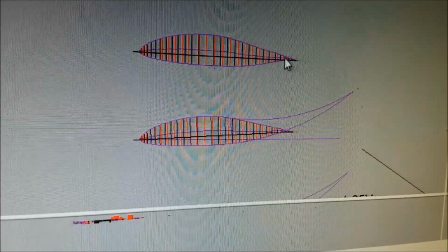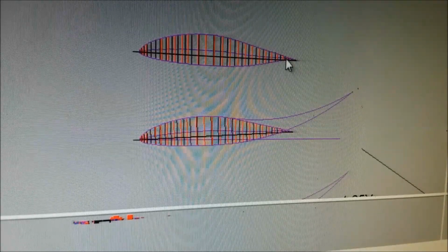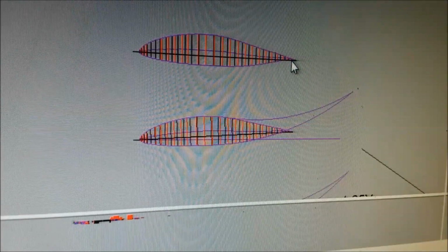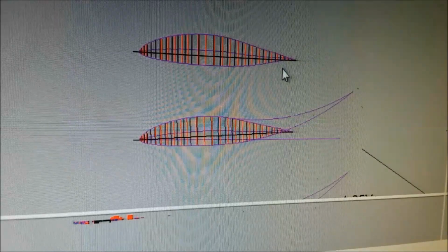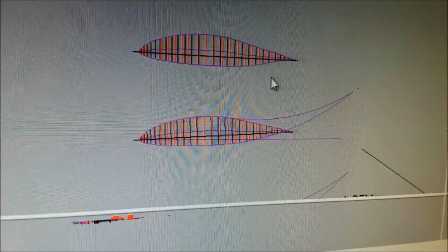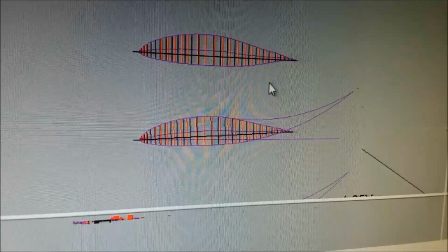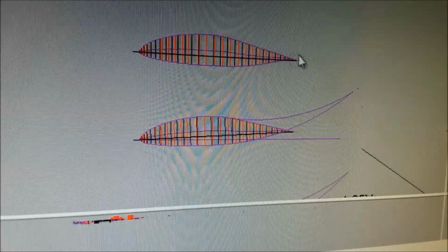So you'll have a 6-layer thick laminate out here with an open place in the bottom that's not matching your thing at all. And then you mix something like sawdust in your resin, or if you're going to a place that sells fiberglass parts, you can get micro balloons. They're just extremely small glass spheres, but they're light and they sand really well. And you just put that in there and then you sand that to the contour.